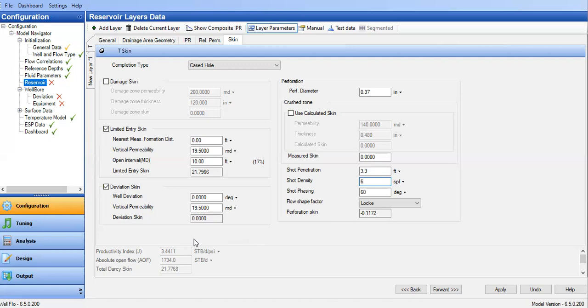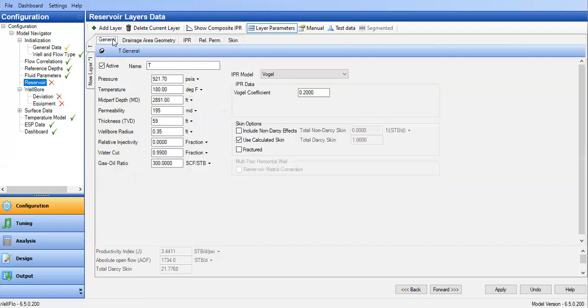So of course, dealing with subsurface issues, we deal with uncertainty. In this case, we have uncertainty, of course, in permeability. That's why you need to correlate the permeability from well log with permeability from pressure build-up, for example, and permeability derived from the well performance, like in this case. So in this case, I assume that the uncertainty belongs to the permeability. So let's adjust the permeability.